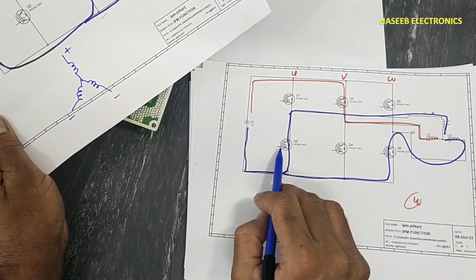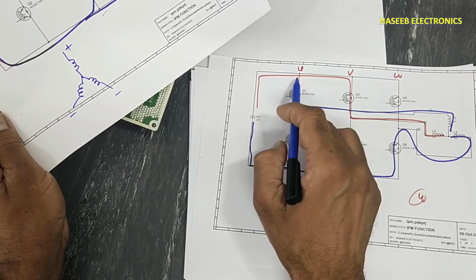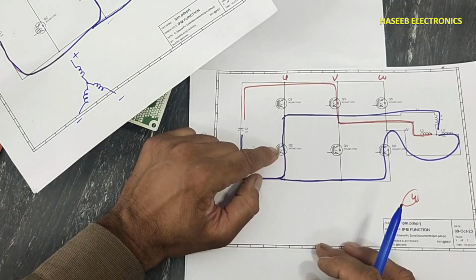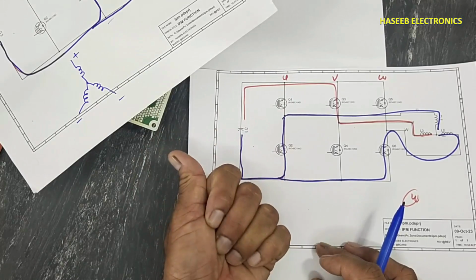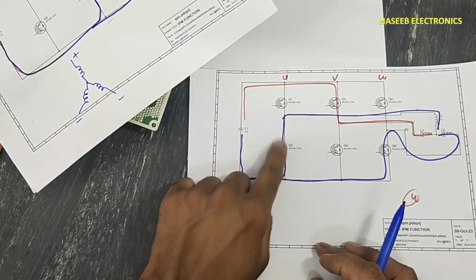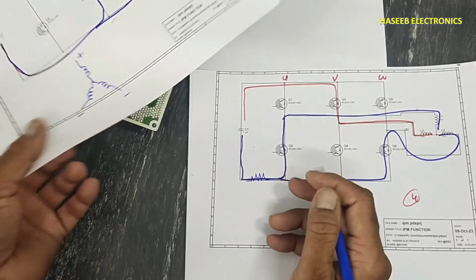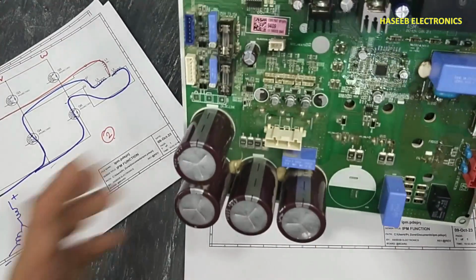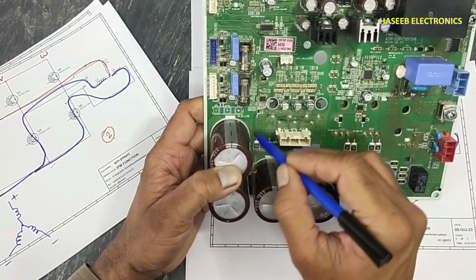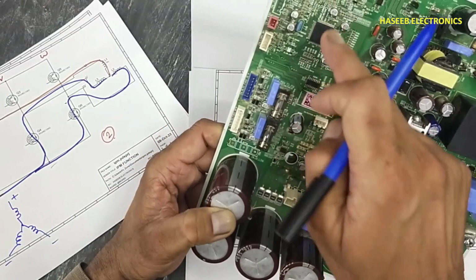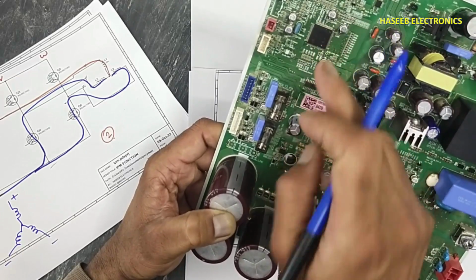When this IGBT turns on, what will happen? This negative voltage will reach directly to the positive rail. Might be it will damage, or due to overcurrent and a good feedback system, good protection system, when overcurrent is drawn, here is a shunt resistance in the board. That is here. Heavy current will flow, this pulse will reach here and this pulse will reach here, and it will provide an inverter current error, that there is high current.